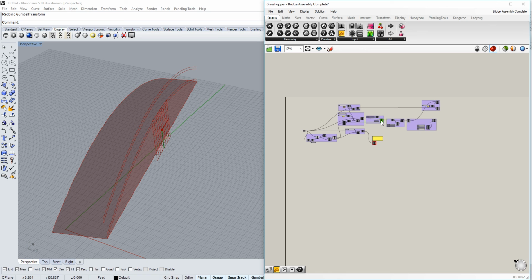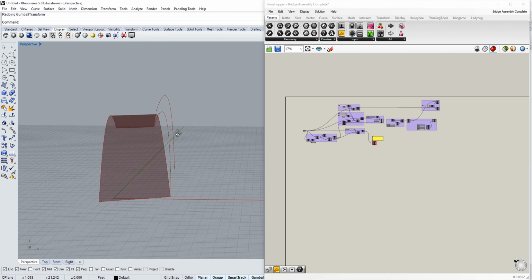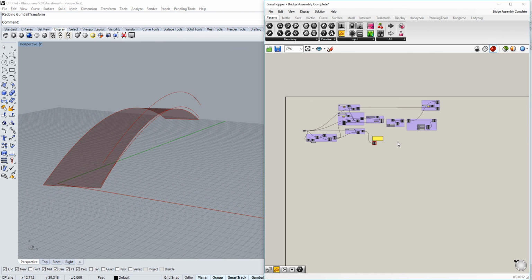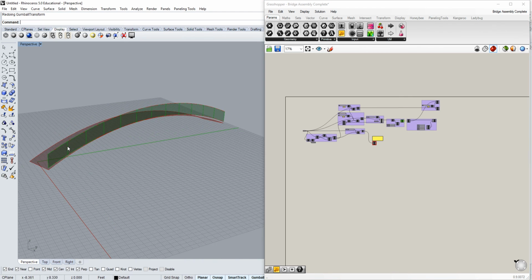And then from there, your next step is going to be to tilt it. So let me turn all of these off so you can see. Whoop, you probably want to hold on to this. There you go. So create one that tilts outward a couple of degrees. And then from there, subdivide it so that you can see a number of individual panels.